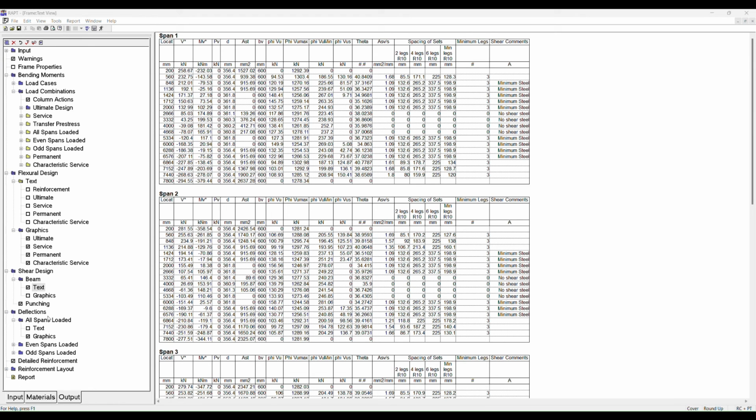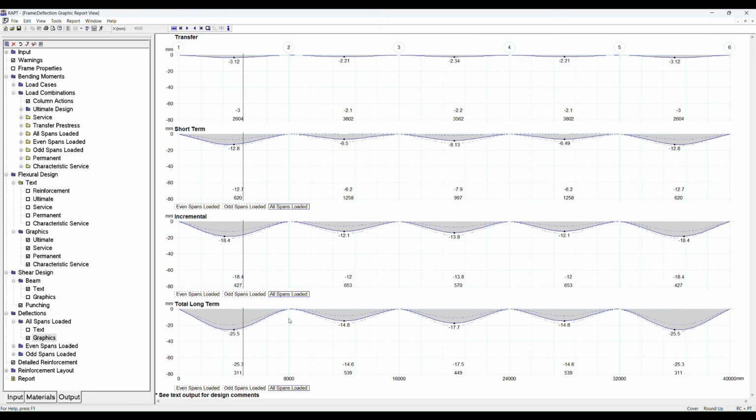So we can go back. Now that we've done that, gone through our shear design, our flexural design, we've looked at crack control, we can now look at our deflections, and these are the deflections based on our design and RAPT's additional reinforcement that it's added as shown in those tables we looked at before. Based on the information that RAPT has given, I should just outline here, the deflections shown are deflections including column shortening for the column below.